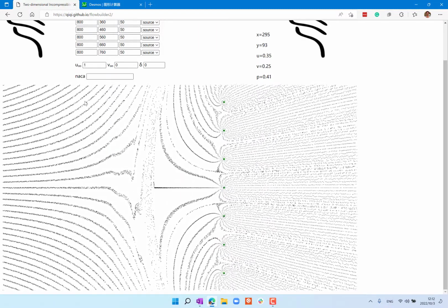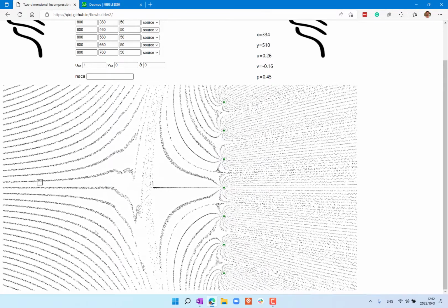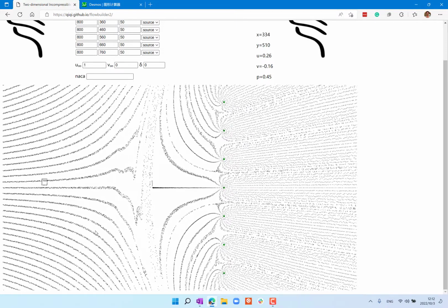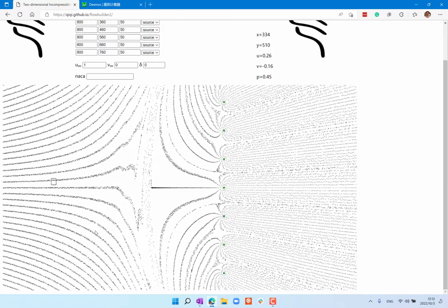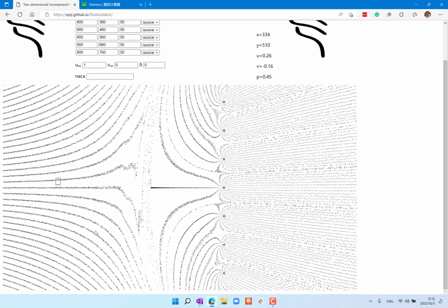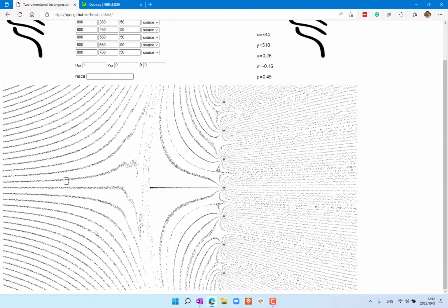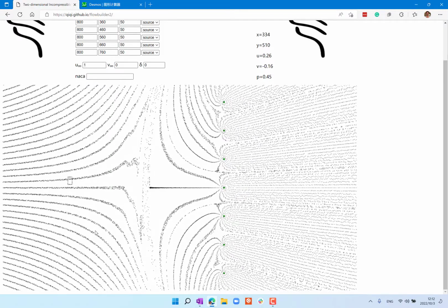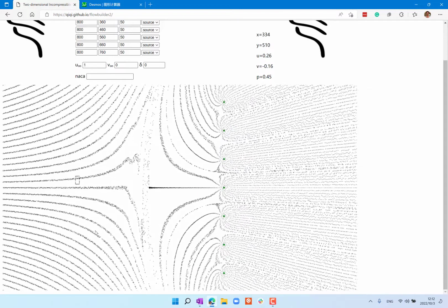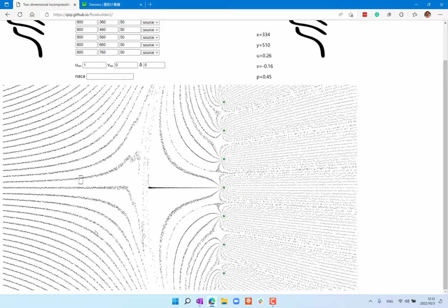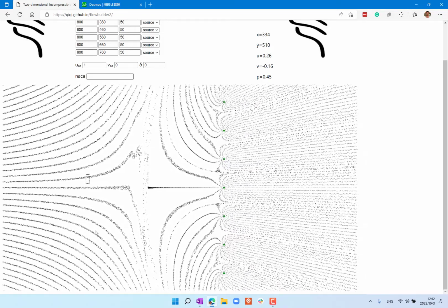And what we can do is, if you click on this, you get a rectangle of particles, and you can watch how it's going to be advected downstream. All right. So we can see what happens. Initially, it's a square of particles, and now it's already deformed into a rectangle, right? This is because the x velocity decreases as you're approaching the stagnation point, right? So the stream tubes widen.